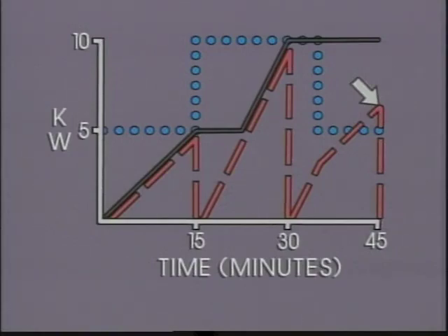6.66 kilowatts is the maximum demand, or average power used, during the third interval, which is more than 5 kilowatts but less than 10. Since the demand during the third interval never reached the maximum demand for the second interval, the pusher did not advance far enough to move the pointer. So the maximum demand indicated on the demand register remains at 10 kilowatts.